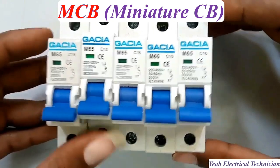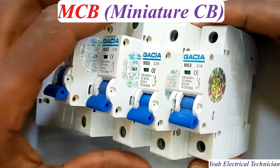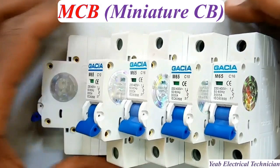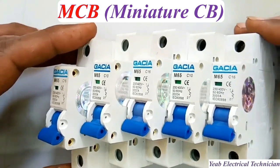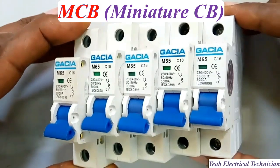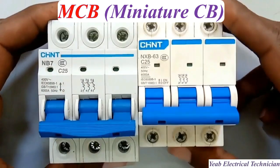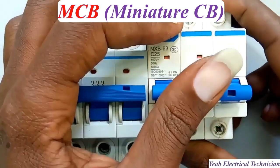It uses two main mechanisms to detect faults. For detecting short circuits, a magnetic coil generates a strong magnetic field when there is a sudden high surge of current. This field instantly triggers the trip mechanism to shut off the circuit. And for detecting overloads, a bimetallic strip heats up from continuous excessive current. When it bends enough, it activates the trip mechanism to break the circuit.